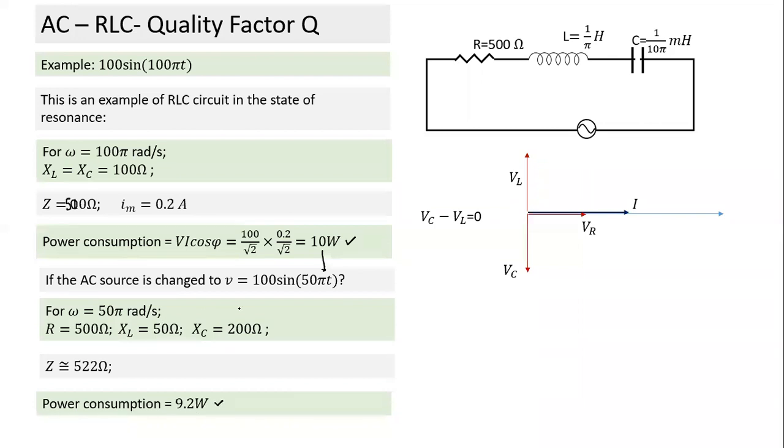So do we notice any difference in the two cases? In both cases, we have dropped the frequency from resonance frequency to half the resonance frequency. First case low resistance, second case high resistance. What is the difference we notice here? The percentage change in power consumption here is small. In the previous case, power became less than a percent. Here it is just dropping by about 8%. Here the change in power is not so significant even when we change the frequency.